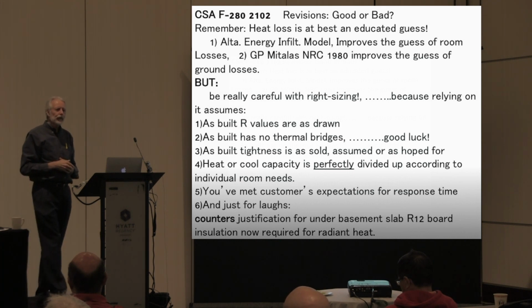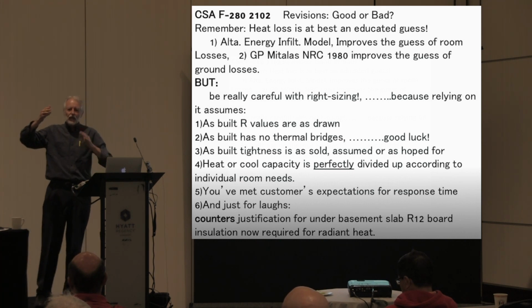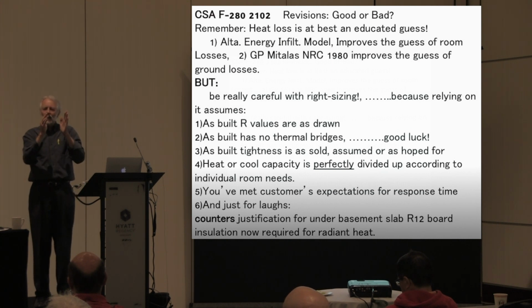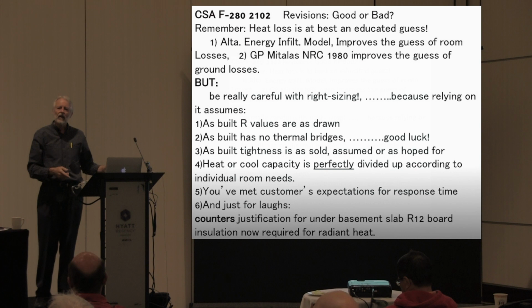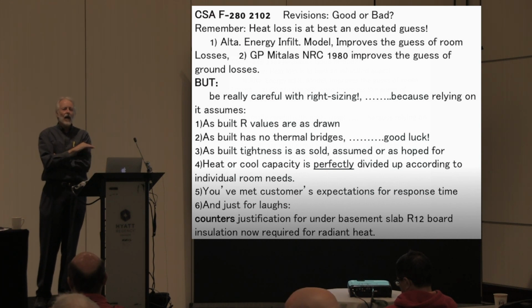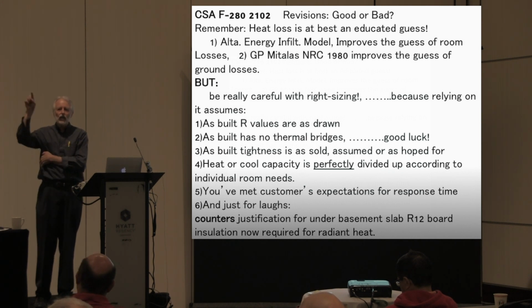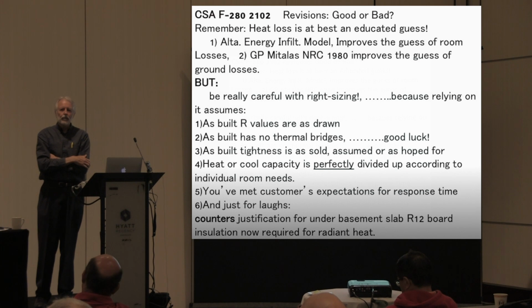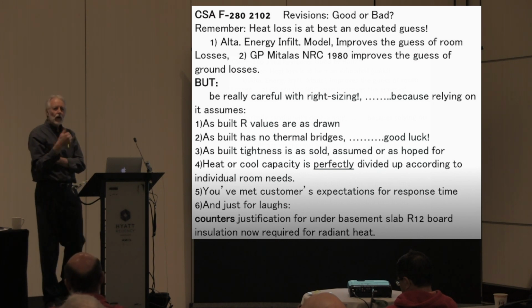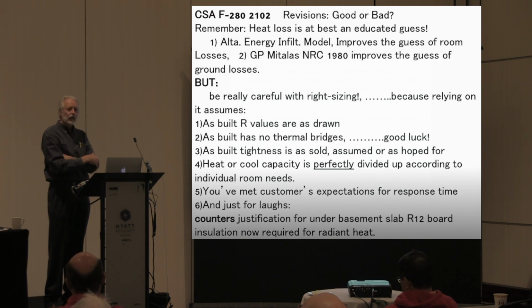Well, what this guy is also saying is that the heat loss of that basement wall above grade is horrifically high, because that above grade wall is seeing the outdoor wind. As you get down and down, the losses per square foot go down to the point where you get into the center of the basement floor, and there's zero losses. The path between the center of the basement floor and the outside is so great, the losses are zero. They just don't even add up. You ask yourself, why the hell should we put R12 underneath the slab? Well, I'll get onto that in a minute.